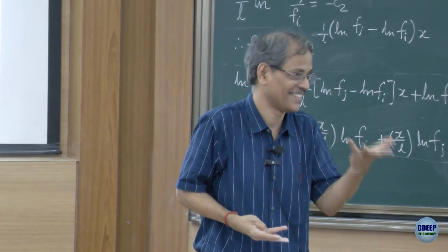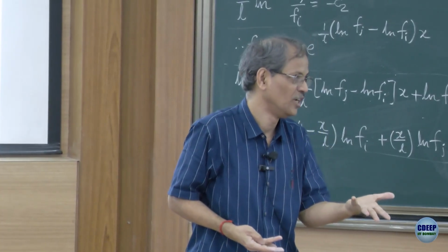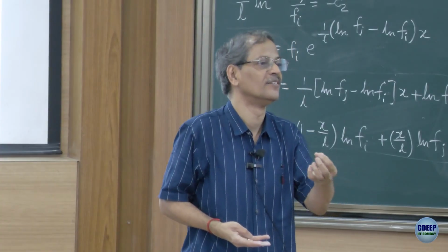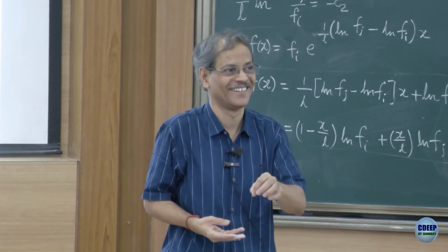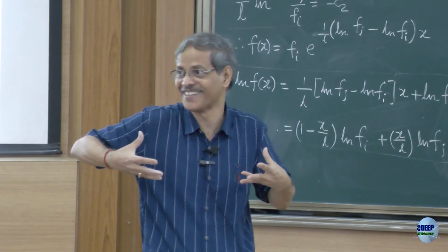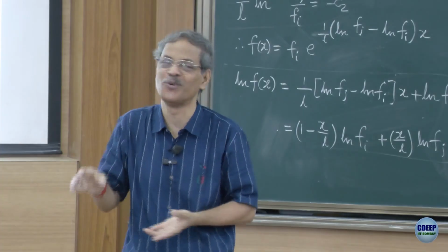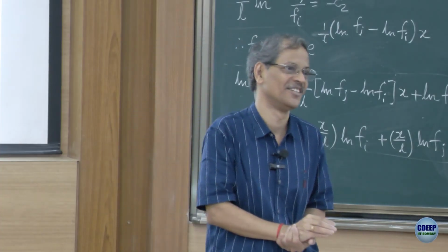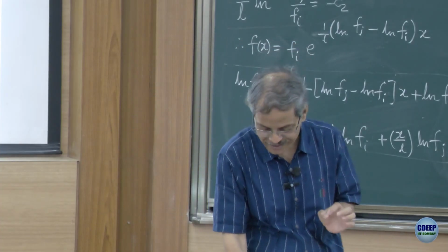How good that mesh is will depend on whether anywhere the element is somewhat distorted and the Jacobian is likely to pose a problem. So, how do you sense this?